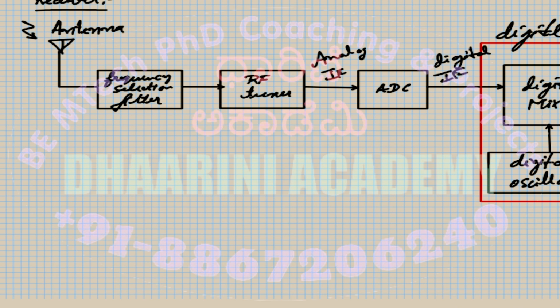Then the timing, because digital is all about timing; the sampling time should be synchronized. For that you need a timing device to recover the original clock frequency used in the transmitter. Those are the two extra components that may be present if you refer to other books or resources. Don't get confused, it is one and the same. Ultimately those two jobs will be done by those devices.